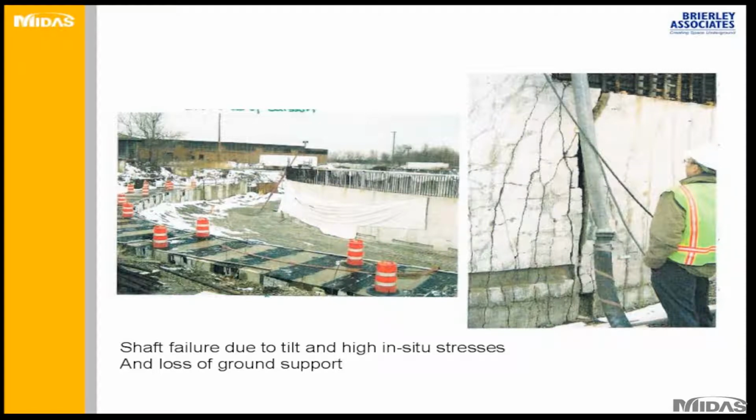This picture relates to my concern about very high in situ stresses. This was one case history which I worked on, where the contractor was building a 150 feet diameter shaft, and when he started hitting the very hard clay at the bottom at about 55 to 60 feet, he started having serious problems trying to advance the shaft.